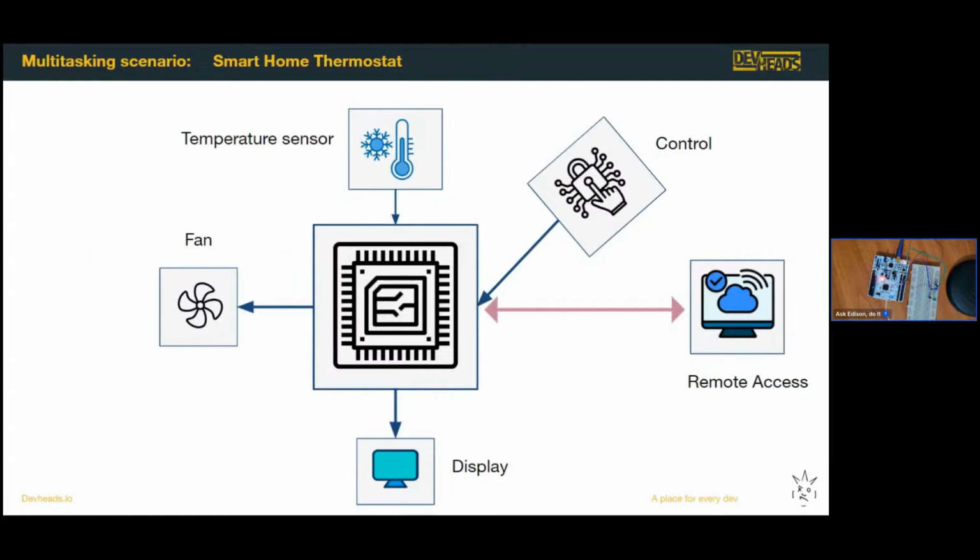You can choose the fan task to have high priority because maybe the temperature is so high, and every time the temperature goes beyond a certain value, you want to override every other task and serve the fan task. I think that has been covered by Zach about preemption, whereby some tasks are dropped by the scheduler so that it can serve the high priority tasks.